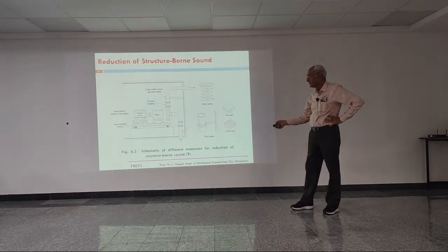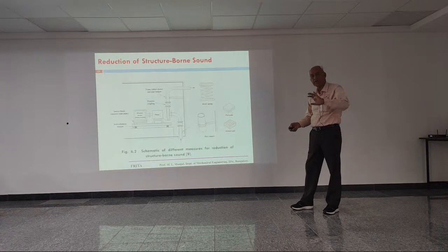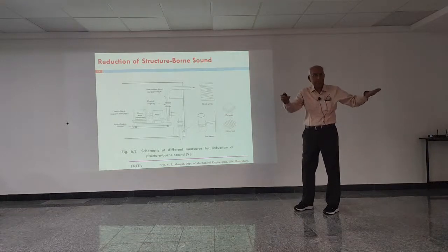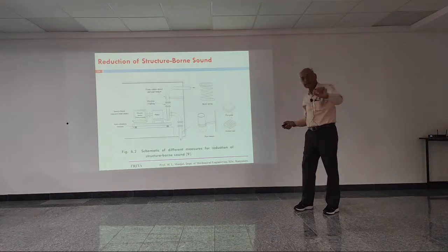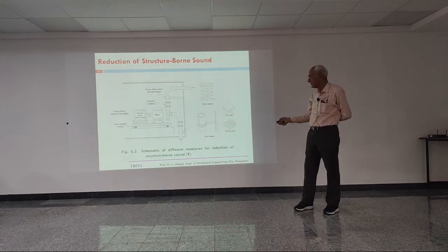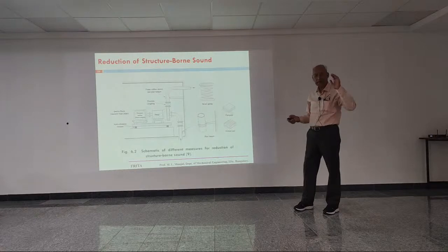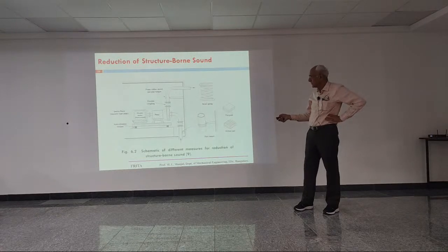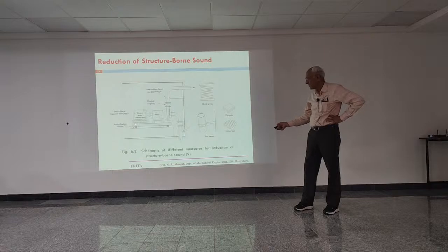You can see here, it may have different kinds of surfaces to finally bring the axes in the same line. Whatever vibration takes place, whatever unbalanced forces come out of the motor as well as the pump, now they act on this plate, and from that plate we don't want this to go to the ground, otherwise that will start moving the structure-borne sound.